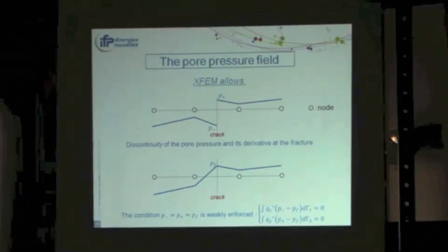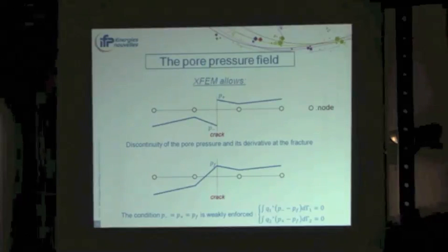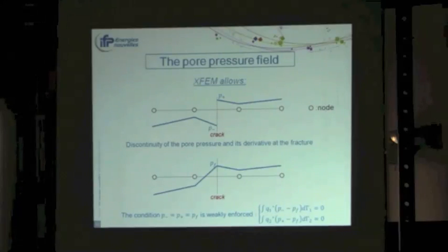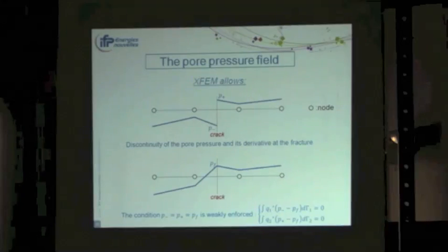Most of the time you consider that there is a lag. So it means that the fluid, that's what is dry, there is no... Yes, the fluid lag. But in your case, you always consider that the medium is saturated. Exactly, yes. So we can even have a negative fluid pressure, which is annoying, but if we take the data of the model, we can prevent this phenomenon from happening if we set the right parameters.